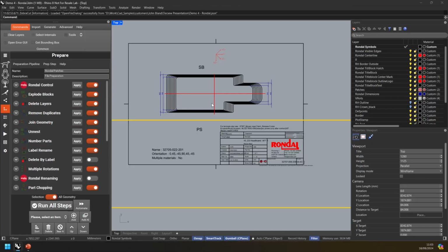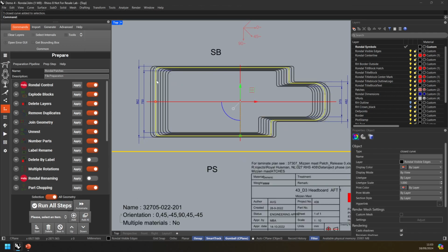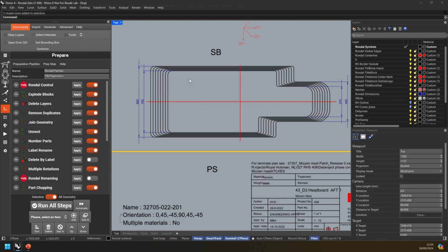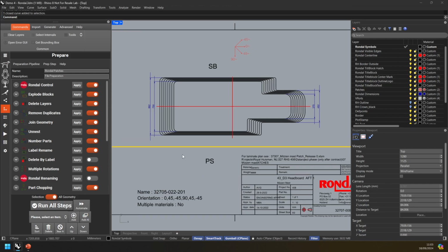This will come from their CAD department, and these shapes here are carbon fibre patches. They're going to be different plies that need to be put together to generate the part. Now, there are a lot of patches and a lot of layers to be made from the carbon fibre, and it's important that when these layers are put together, the orientation of the carbon fibre, because there's a grain in it, needs to be differentiated every time.